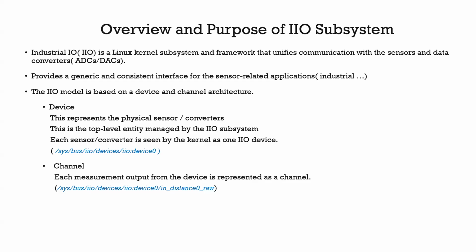You have to take care of memory management, then interrupt management, then synchronization, data handling. If data is coming in very fast, you have to maintain that data in a buffer. So the IIO subsystem provides you all these features. You just have to configure and hook up your core driver with them.